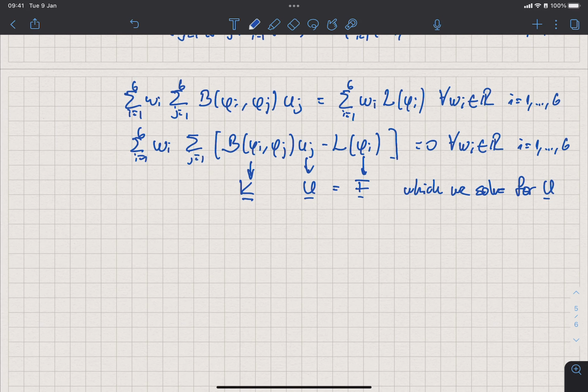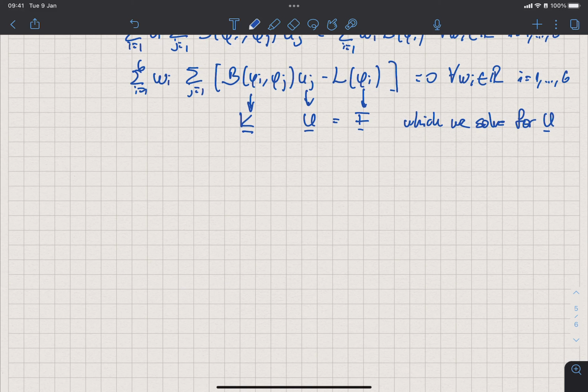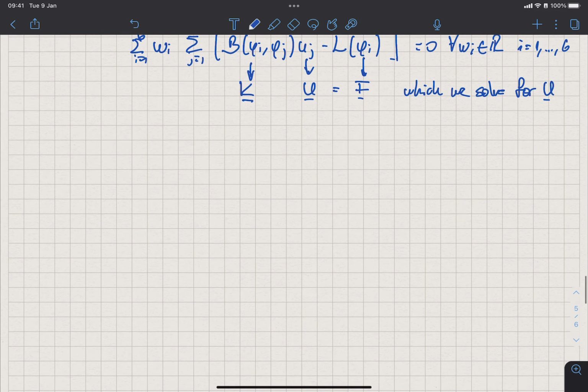So there is an alternative approach to get to the finite element equations, and I actually like to do both so that you see the same from different angles. So what I'm going to do now is consider the equilibrium of one single element. Then after we do that, we're going to see what happens when we assemble the contribution of all elements, and then we are going to obtain the system of linear equations, Ku equals F, in a different way. So let's consider the equilibrium of one element.